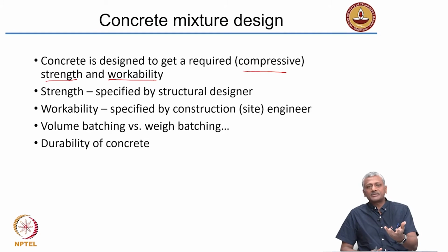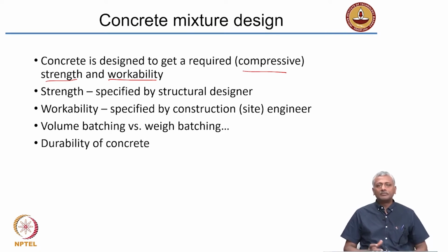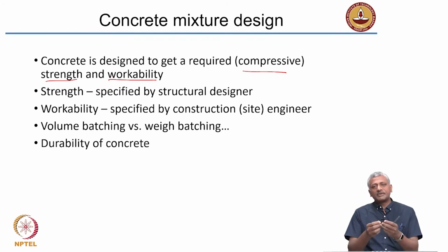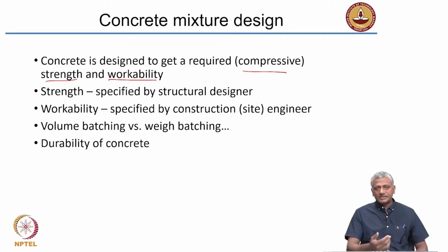Now you can compare this to something that you see at home when your mom does cooking, right? When you have flour and you mix water into it, if you mix just the right amount of water, the flour is nice and pliable. If you mix too much water, what happens? The flour becomes very sticky and starts flowing. So that's the same concept in construction also. If you add the right amount of water, you get the correct amount of workability. If you add too much water, the ingredients may start separating out. If you add too little water, your flowability or consistency may not be enough for the concrete to satisfactorily fill up the formwork.